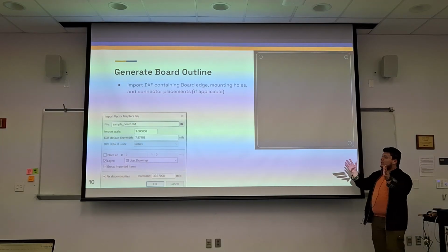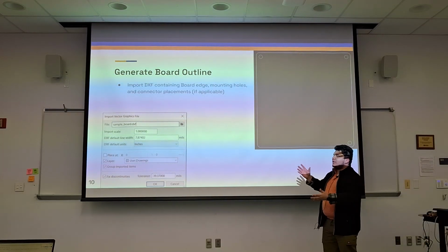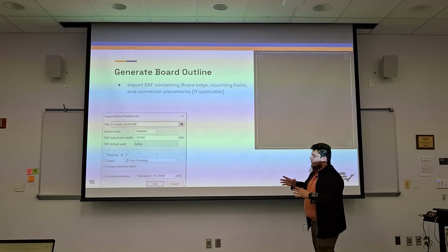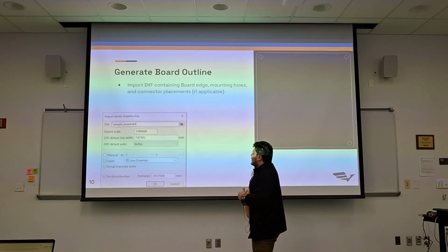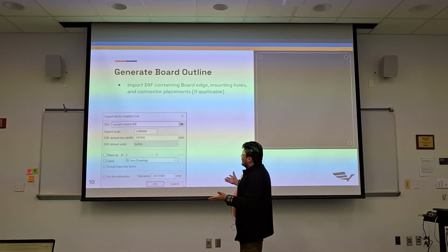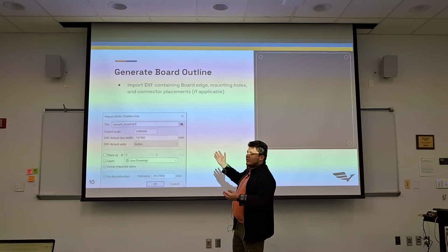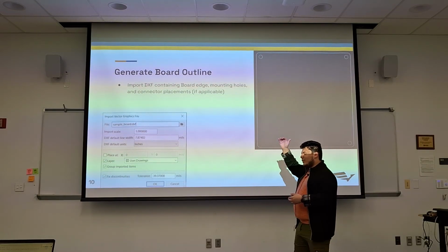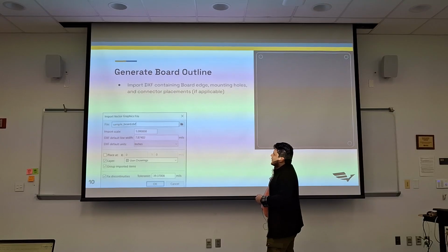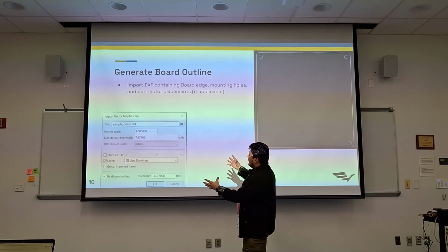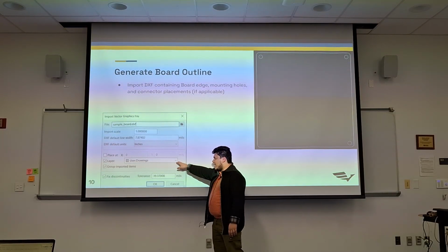So first and foremost, kind of an obvious thing, we've got to get our board outline, which is usually in our edge cuts layer. In case y'all haven't seen it, you have to import the DXF, which is under File, then Import, Graphics. And so you get your DXF, and normally you want to actually put it in edge cuts.